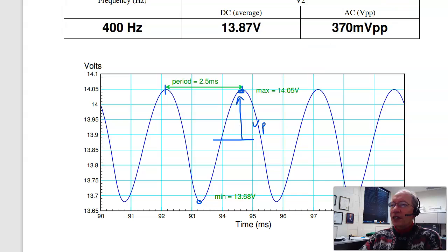If I find the RMS voltage, that'll be roughly the peak divided by square root of 2. Now, not exact, not a pure sine wave, but that'll be pretty close. So that's V RMS. So you got to label your answers. And in this class, we're using peak to peak voltage. That's a little bit easier to see on the oscilloscope.